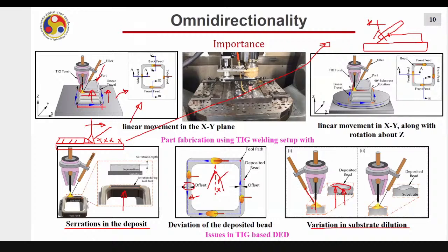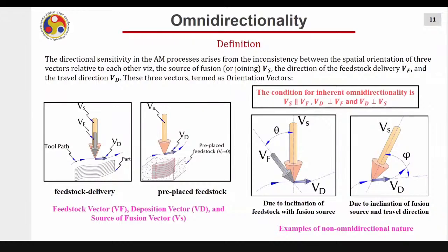Now, if you do not rotate it, what will happen when the feeding mechanism changes? Earlier you were getting the less penetration on the left side. Now you will get the less penetration on the right side. So there are issues. And this is only what I discuss about DED, the issues are in many places, and I'll discuss each and every process in detail.